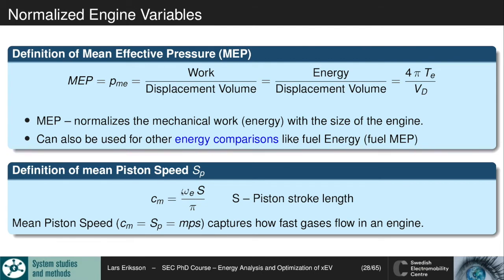Here we're looking at the angular velocity of the piston. We're normalizing it with rotations, and S is the stroke length. How far does the piston travel? That's the stroke of the engine. So we're looking at how fast the piston is traveling on average over a cycle. Then we're normalizing it towards a velocity that will be related to the speed of sound.